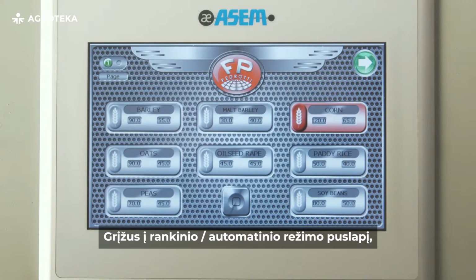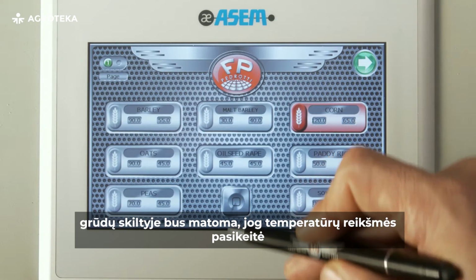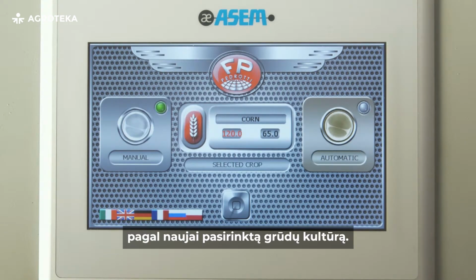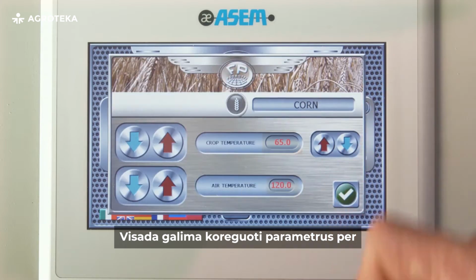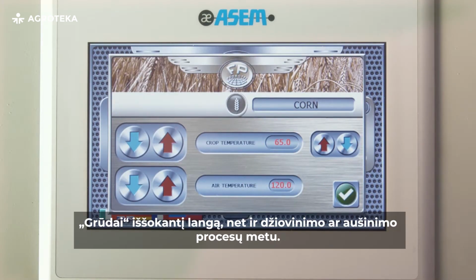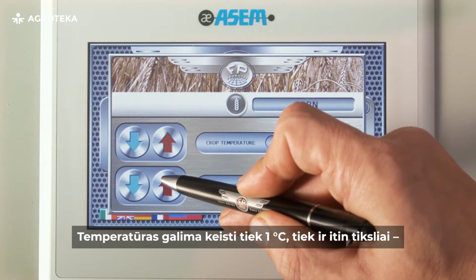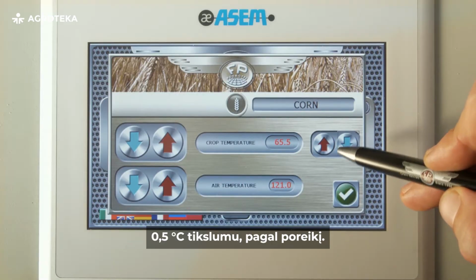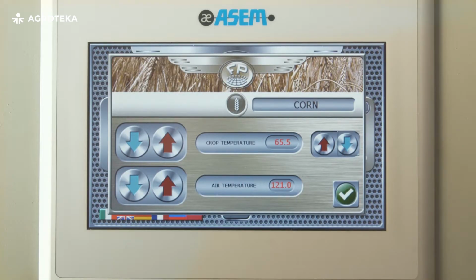Going back to the manual automatic page, it will be possible to see that in the crops area the temperatures values have changed according to the new crops selected. It will be always possible to change the parameters from the crops pop-up also during the drying and cooling processes. It is possible to change the temperatures by 1 Celsius degree or even 0.5 as desired.